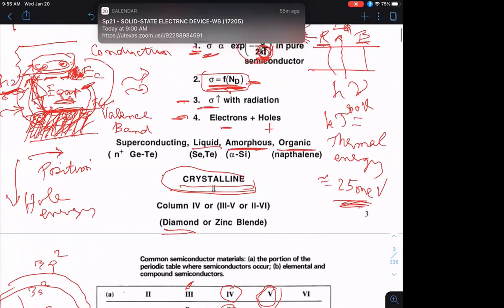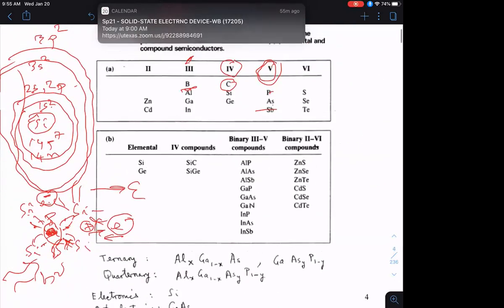In terms of the energy band diagram, now we introduce energy levels close to the valence band. You can easily excite electrons from the valence band to these. These are called acceptors because they can accept electrons from the crystal. And in the process, it creates these positive holes. And if you have a p-type doped region, positively doped region, right next to an n-type doped region, that's what you get in a p-n junction.